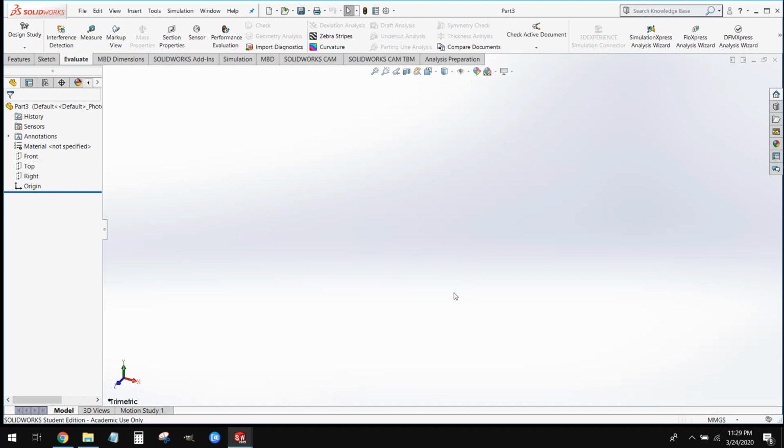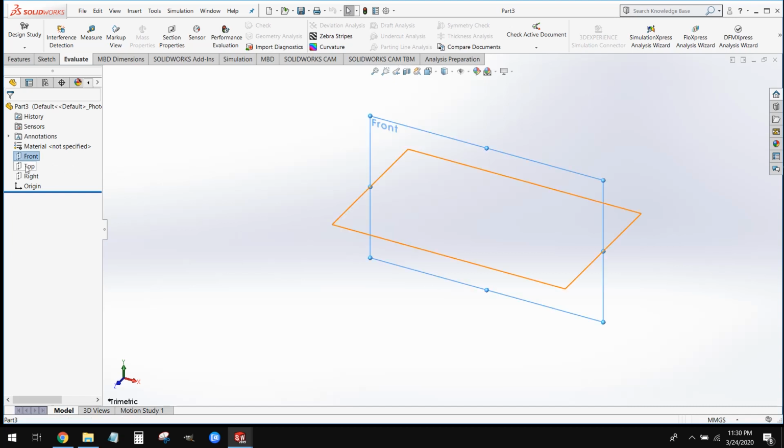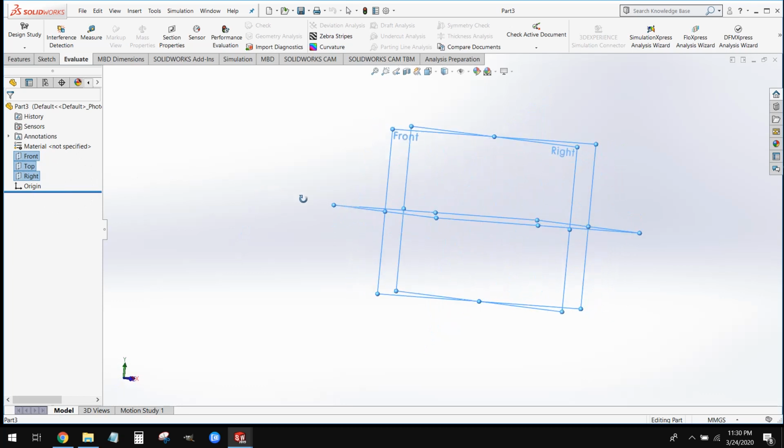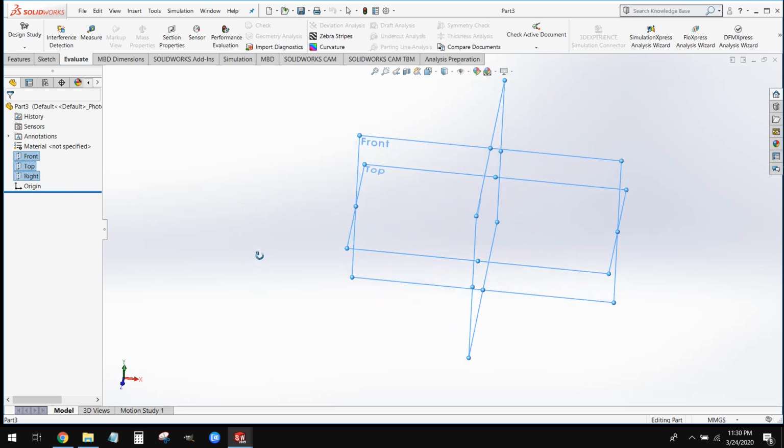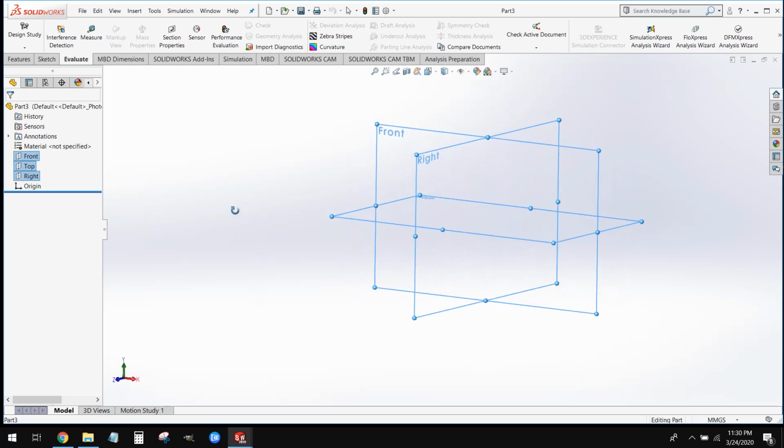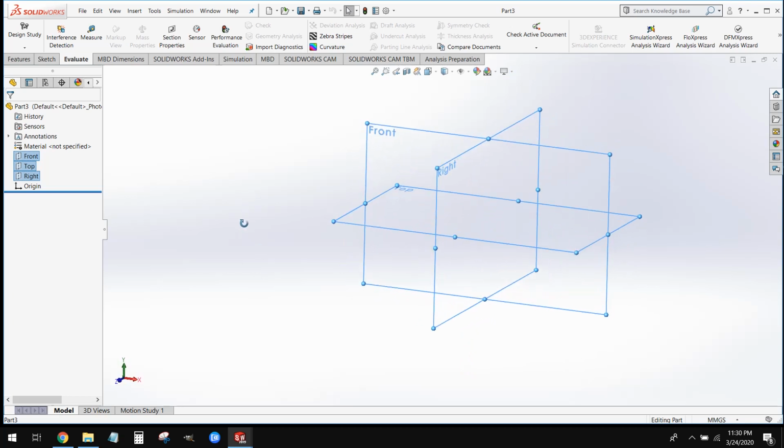So like I was saying earlier, what we're going to first start with is a 2D sketch of that square base. Now if we look on our left-hand side over here, we'll see that SolidWorks gives us 3 planes to do those sketches on: a front plane, a top plane, and a right-hand plane. These planes are like pieces of paper that we can create our sketches on.